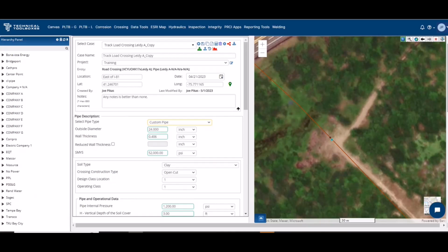This served to reduce the load on the pipe itself and allowing the surrounding soil to support a portion of the overburden. And of course, overburden, and you'll see in the program, is a function of the following parameters: the weight per unit volume of backfill, trench width, load coefficient, burial depth, friction coefficient between the backfill and trench.